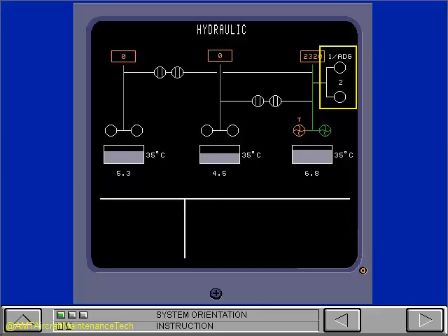The auxiliary pumps use two of the same displays as the engine pumps. A white circle shows that the pump is off, and a green circle with green veins shows that the pump is on. Schematic lines show the condition of the hydraulic pressure lines. The schematic lines are green when the applicable pumps are on and the pressure is more than 2400 psi for 2 seconds. The schematic lines are white when the pumps are off.